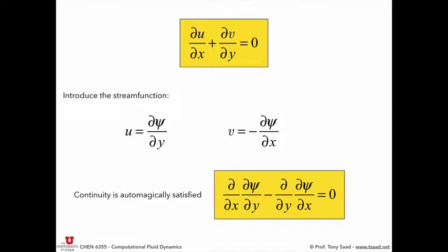Now, there's a physical meaning for the stream function. The stream function represents the lines that are tangent to the velocity vector field. And the difference between two streamlines gives you the flow rate between these two streamlines. But you should have studied that in fluid mechanics. But if you haven't, forget about that for a moment. Just think about what this ingenious operation does mathematically.